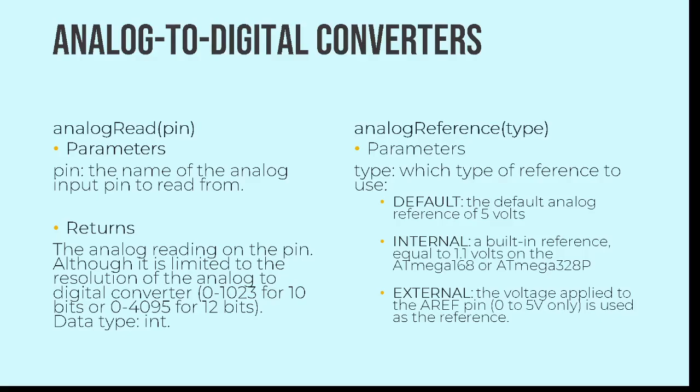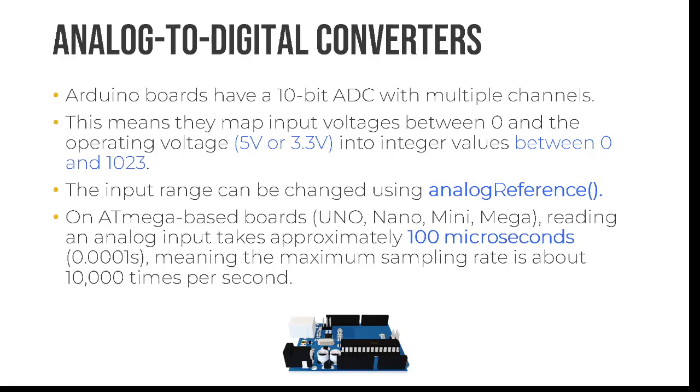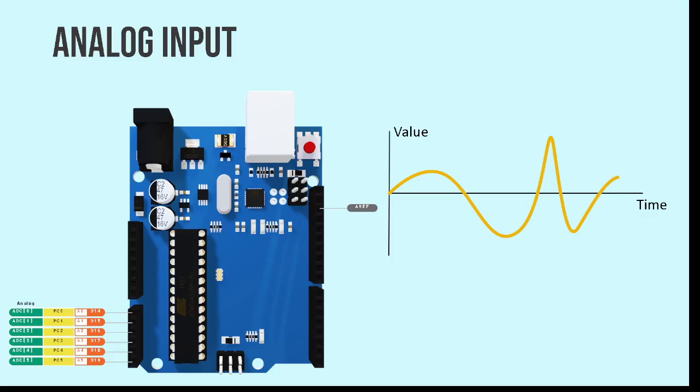And we have a third option, that is to connect an external reference, right? So you can connect whatever voltage you need to generate your conversion, right? 3 volts, 2 volts. To do that, you have to connect your reference voltage to a pin here, called AREF. If you remember, in Proteus we were connecting that to 5 volts, right? It's because we use that. But if you have a specific sensor that delivers a voltage between 0 and 2.1, you could connect 2.1 there, and you use all your ADC conversion range right there. So you will be more exact.